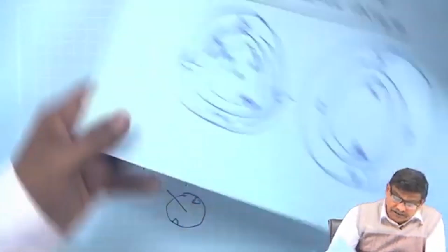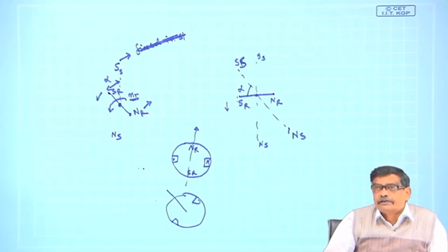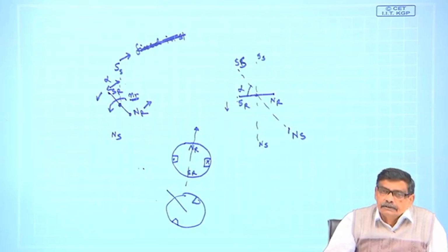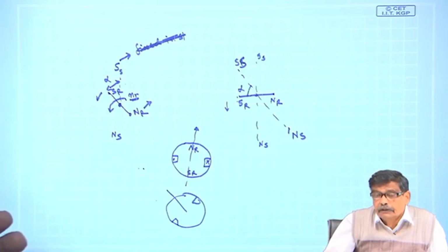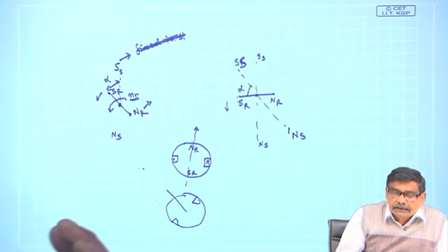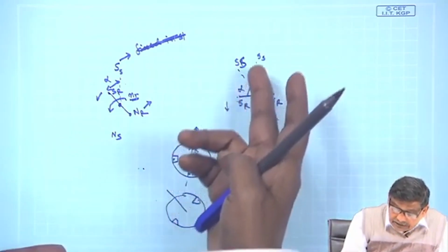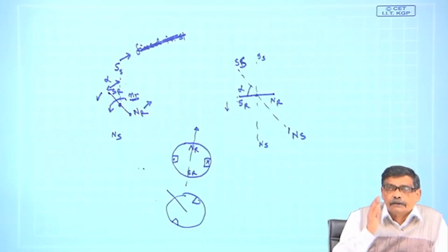to produce sustained electromagnetic torque, you must see that the stator field and rotor field are moving at the same speed with respect to a stationary observer, such that the relative speed between them is 0, no matter in which position the rotor is. The angle between the stator and rotor field must remain constant.